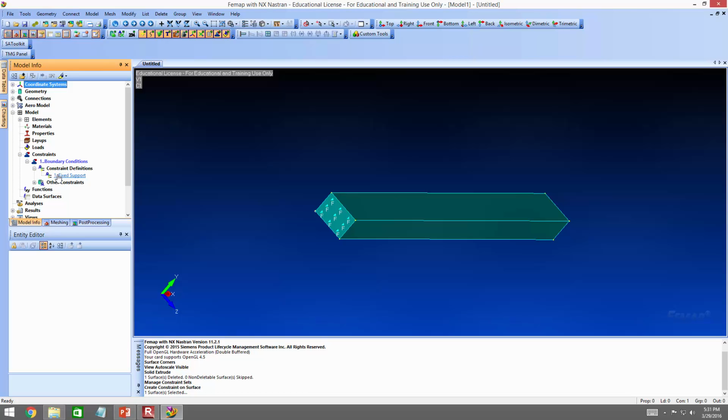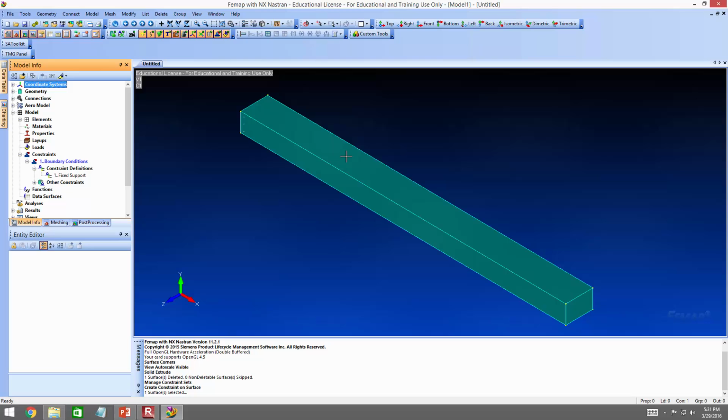All right. Is everybody good? So again, if you hit the wrong surface, that's no big deal. Okay. So I'm going to go back to that isometric view so that I can do that. Okay. All right. Those are the boundary conditions. Now let's look at the loads. What loads are applied to this beam? We have this 0.2 KSI. It's a pressure load, right? It's a pressure on top of the beam.